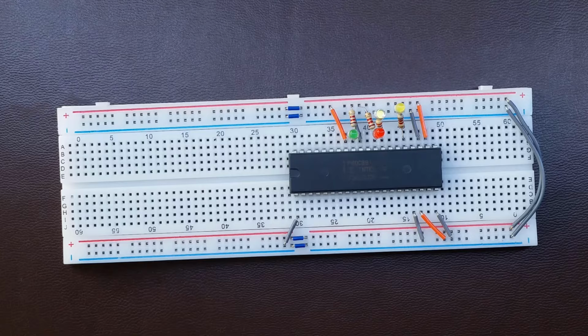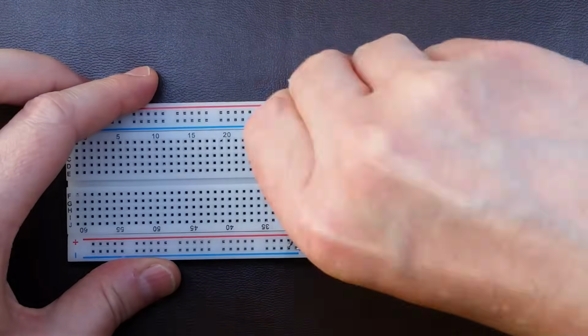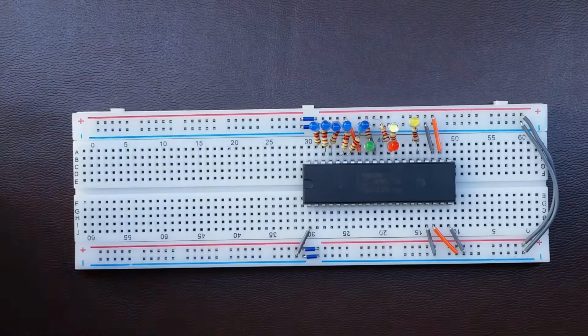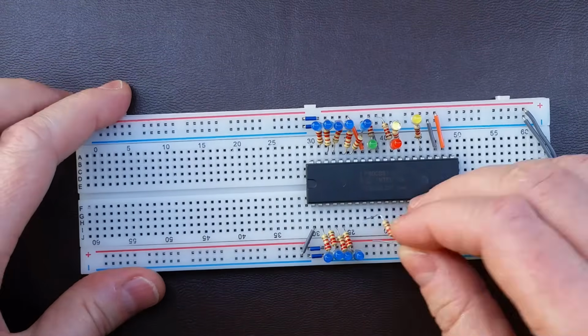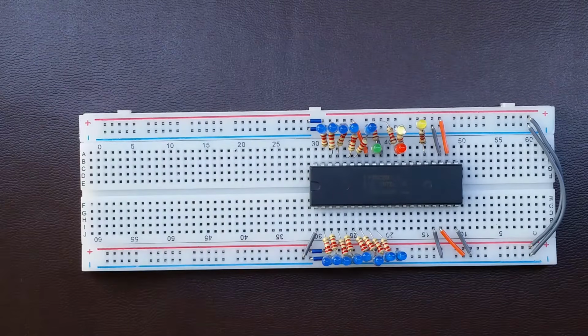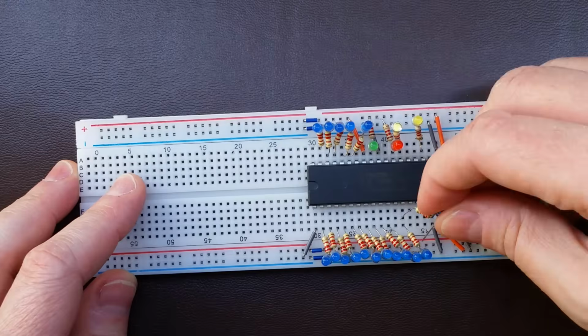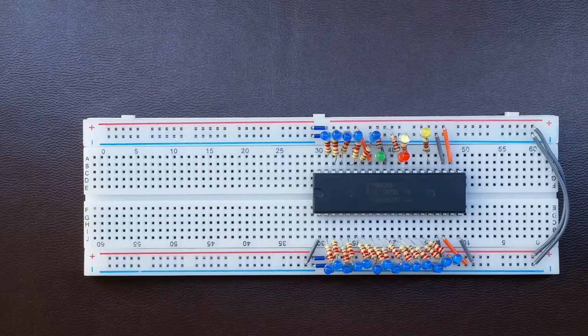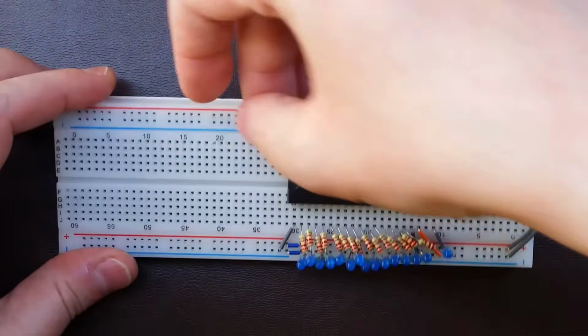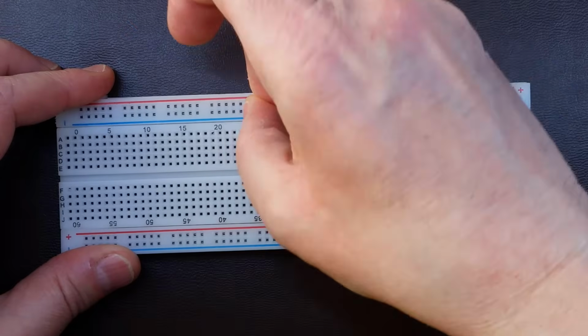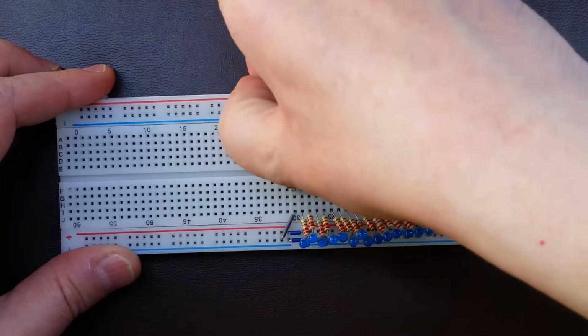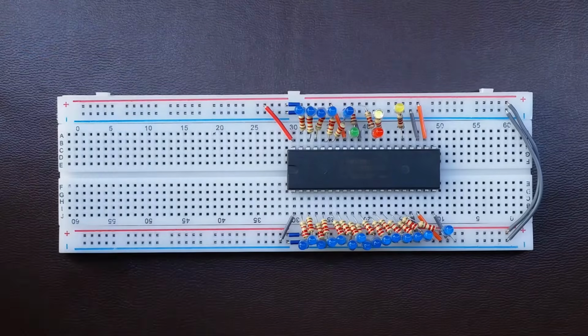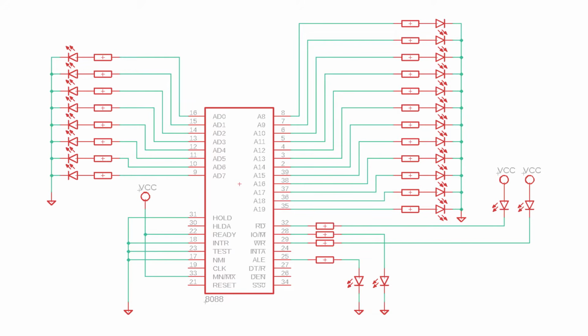Finally, pin 34, SS0, is a status line that we don't need to use. Now we're ready to hook up 20 LEDs to the address and data lines to see a complete state of the CPU bus while it works. I almost completely forgot about pin 40, the VCC, so the power supply. There you go. This is what we currently have on our breadboard.